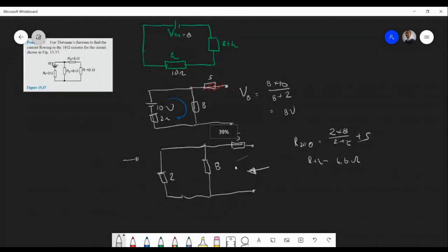So it's just important to note when you're adding the resistance, you have to be very careful over here with this kind of stuff. So you remove that, you're looking in, but you add in the other way. I don't know why they actually say looking in, but we will get more practice on how we do that. Then we have this value, we put R-Thevenin over here, 6.6. Of course, you could have solved this using another approach, but this is the Thevenin approach. It's a series circuit now, and the current going through the load is going to be 8 volts divided by 10 plus 6.6, so that's 8 over 16.6, nearly a half or something. So 0.481927 amps. That's the Thevenin approach, basically in a nutshell.